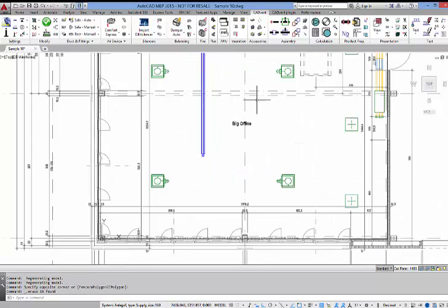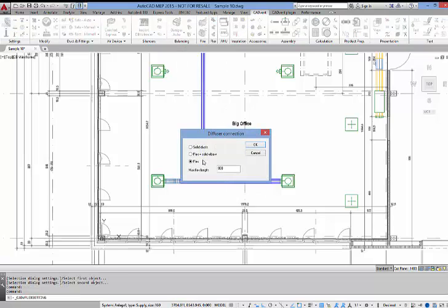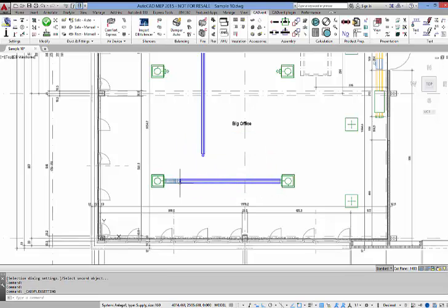So how do we connect it now? It's quite simple. Connecting 2 points, 2 open ends, is a simple command. I can just say, please connect 2 open ends, and then I click on the first end and the second end. Inside CADvent, we have the functionality to connect air devices with flexible ducts, and the length of the flexible duct should be not more than 800 millimeters. This function is used when I connect 2 devices like here only one time. So what I have to do is delete this piece of duct and use the same function once again.